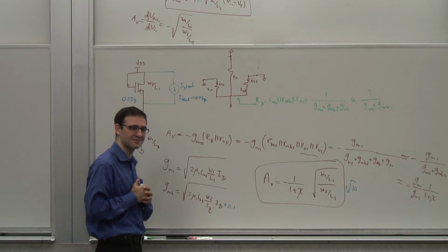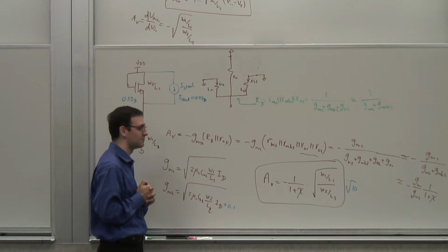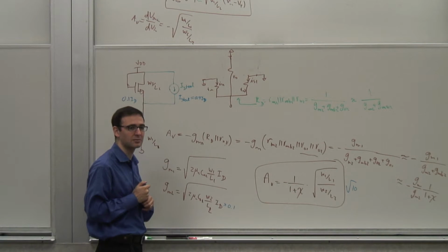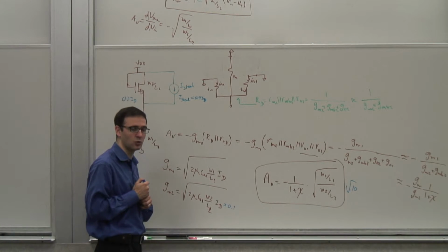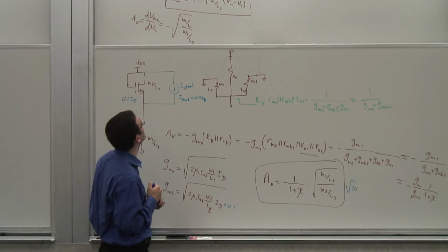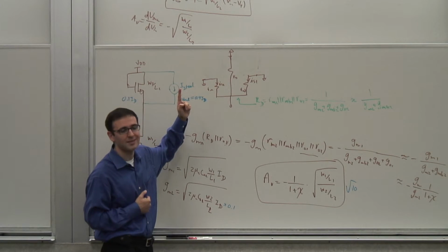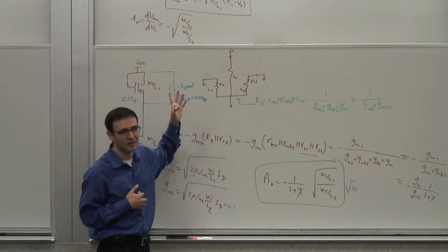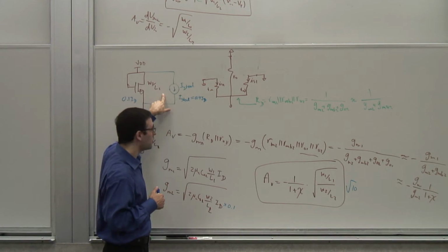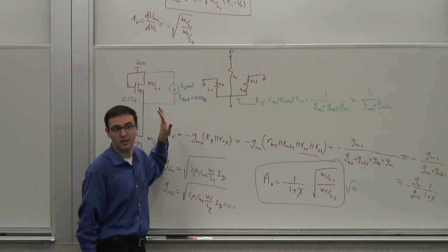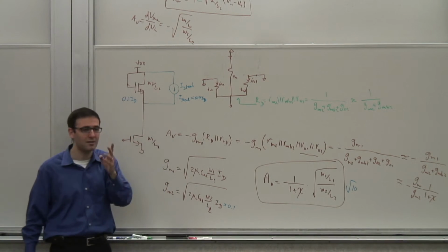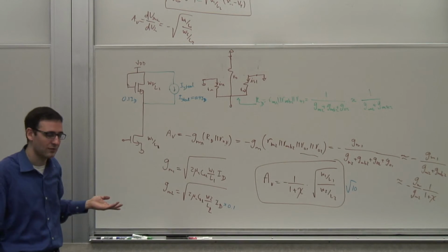Yeah. But with this method, though, would you be able to keep the linear performance? Because if you equate the drain currents, it doesn't come up. No, you won't be able to keep the linear performance, but you are going to get more gain. That's a very good observation. You will lose some linearity if you do it the way I've shown. There are other ways of making it more linear, but if I do it this way, I will lose linearity, as you pointed out, correct? But still, I get more gain. So sometimes I care about gain without linearity. So if that's the case, then I will do this.